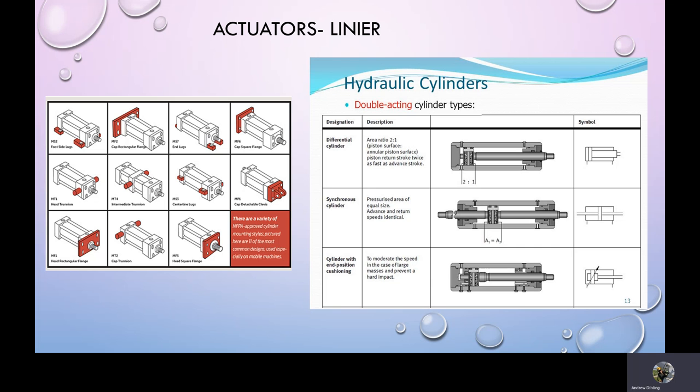on conveyor systems. And we also have cylinders with cushioning on there, and that's a variable cushion because the arrow is going through it. And the cushion is designed, remember, to slow the end position. So as the cylinder comes to an end position, it doesn't have a big full stop. It coasts to a stop at the end, which is very useful.